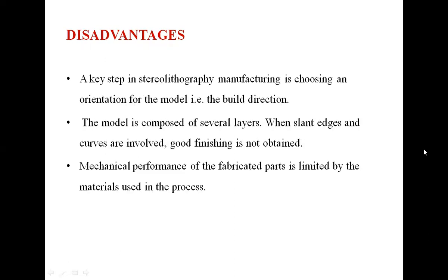Next one is disadvantages. A key step in stereolithographic manufacturing is choosing an orientation for the model, that is the build direction. Model is composed of several layers, while slant edges and curves are involved. Good finishing is not obtained. Mechanical performance of the fabricated parts is limited by the materials used in the process.